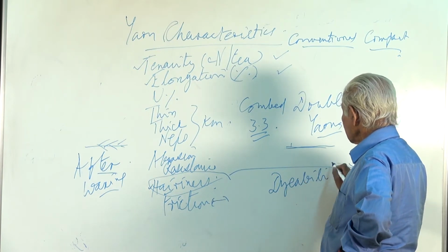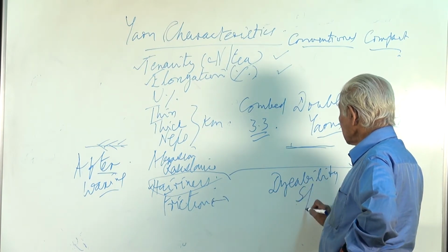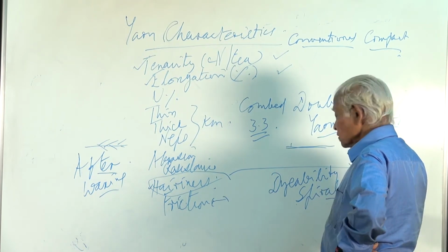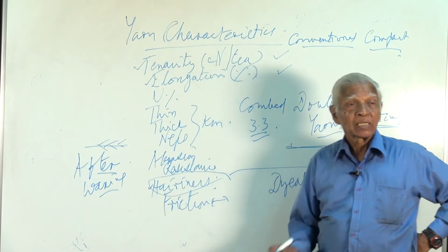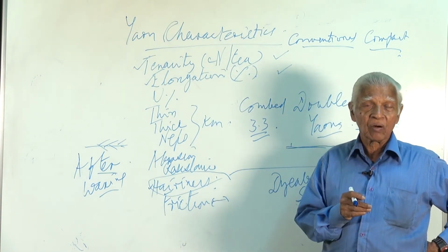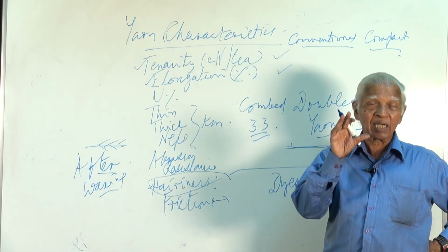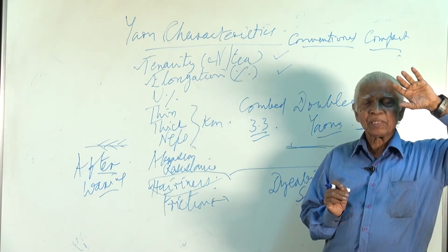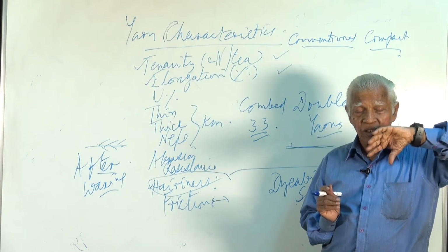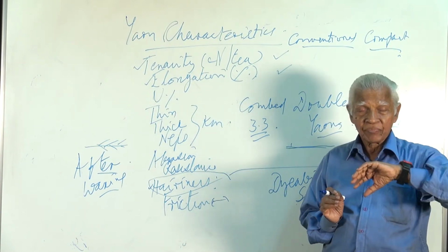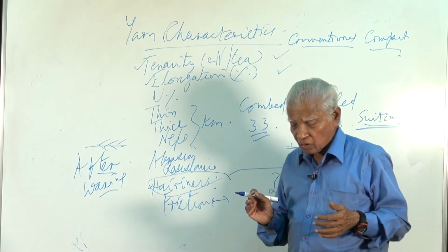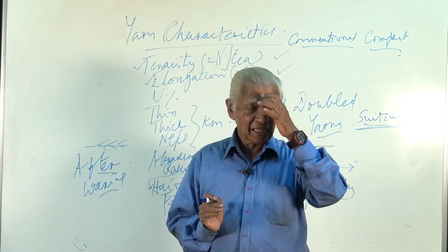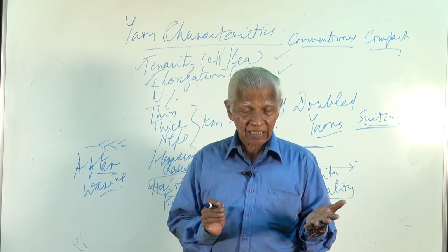And there is a defect in knitted fabric called spirality, which is avoided by using low twist yarn. So the Hong Kong Polytechnic did a very comprehensive work on these low twist yarns, or low torque yarns as they are called. They fixed an attachment to the ring frame in order to produce low torque yarns. And the potential of these low torque yarns was studied in fabrics like denim, and also their dyeability was assessed.